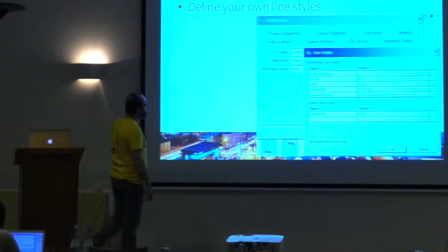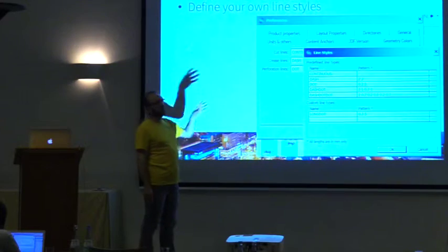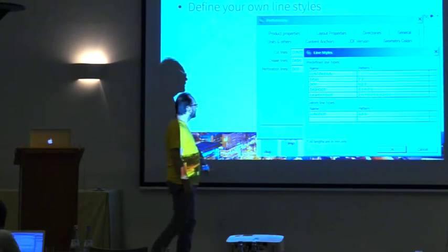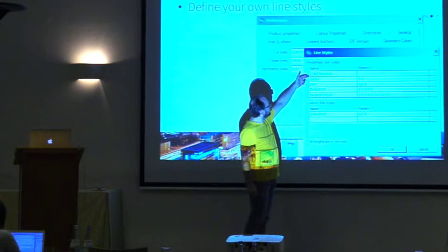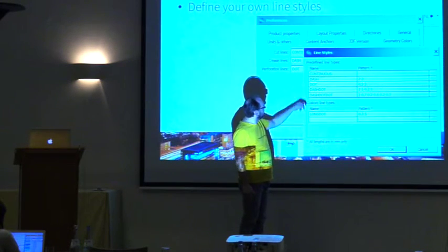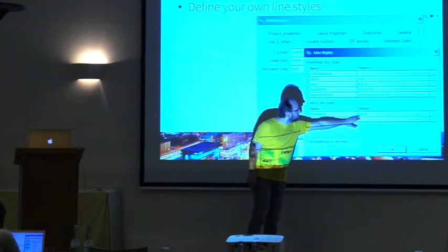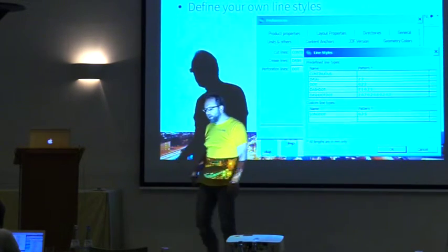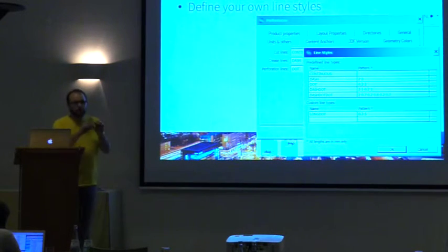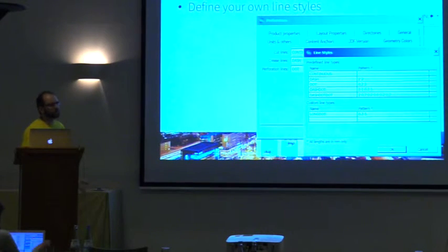What you have in version 8 is the ability to customize your line styles in there. Sometimes you want to do something specific. What I've done here is instead of the continuous or the dotted line or a dash dot line, I've created something else. So you can simply here specify a pattern that you want to use, and that allows you to create a custom line type if you need that for an export that you do for a cutting machine, for example. You specify these line styles once. They are set up in the preferences, and then once they are set up there, you can use them anytime you export a die line shape from within IMP.